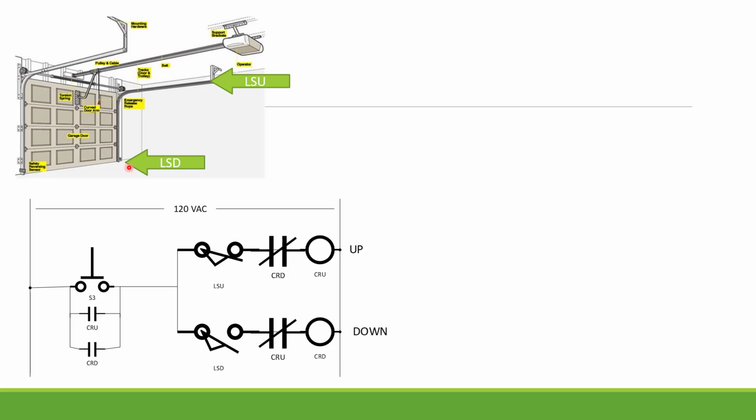There are some called proximity sensors that serve the same function of detecting a position, but those can work off of induction or capacitance, so you don't actually have to touch it to energize it, to make it change states. You just have to be near it. But in this case, I've got limit switches that actually have to be moved by physical contact.